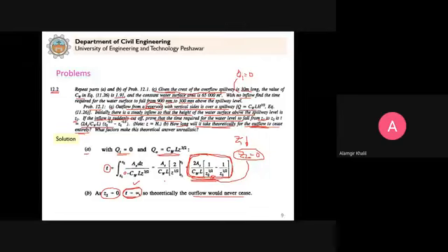So what could be the possible factors that give us this unrealistic solution? Factors which make this theoretical answer unrealistic include surface tension, surface ripples, evaporation, leakage, and seepage losses. We already know that from a reservoir there can be evaporation from the water surface. Similarly, there can be water seepage down into the soil. These factors we did not consider while calculating the equation for the time, so they can be responsible for why we get the time as infinity.